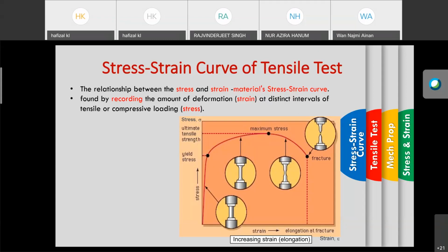The term at this point we call the yield stress. At this maximum y value, we call it the maximum stress. Then the information of fracture is somewhere here, whereby the necking is the process of the break of the material. As you can see from this position, the original standard sample slowly deforms in the middle and finally breaks.